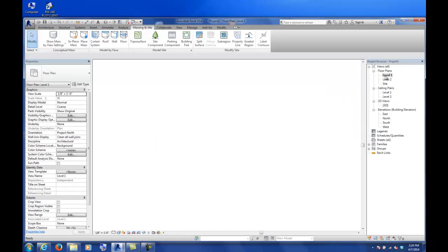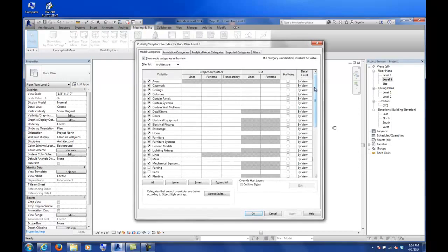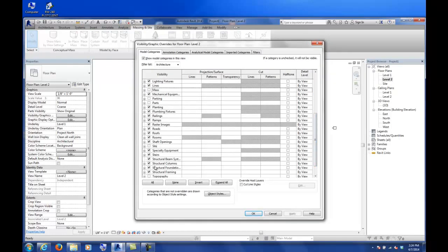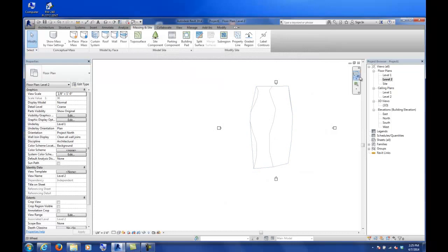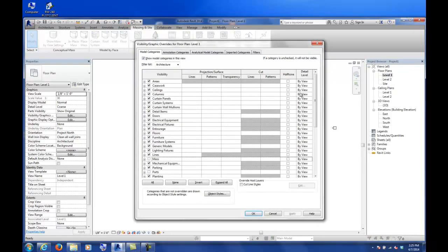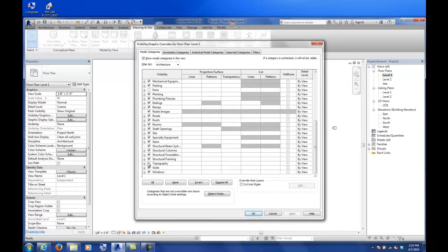But when you start cutting sections, in my floor plan views, your topography is probably going to be turned off. So in your visibility graphics, you want to go under topography there and turn them on. But what I was going to get to here is visibility graphics, topography.